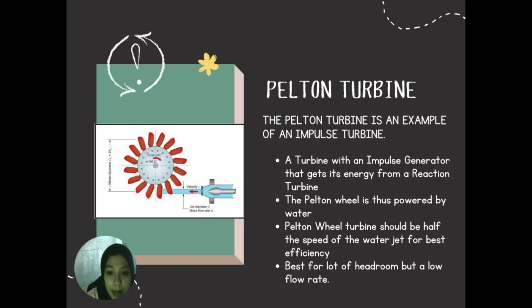With a turbine like this, more electricity might be created. In an impulse turbine, all of the hydraulic energy is converted into kinetic energy by a nozzle, whereas only a small percentage of total energy will be converted to kinetic energy in a reaction turbine.